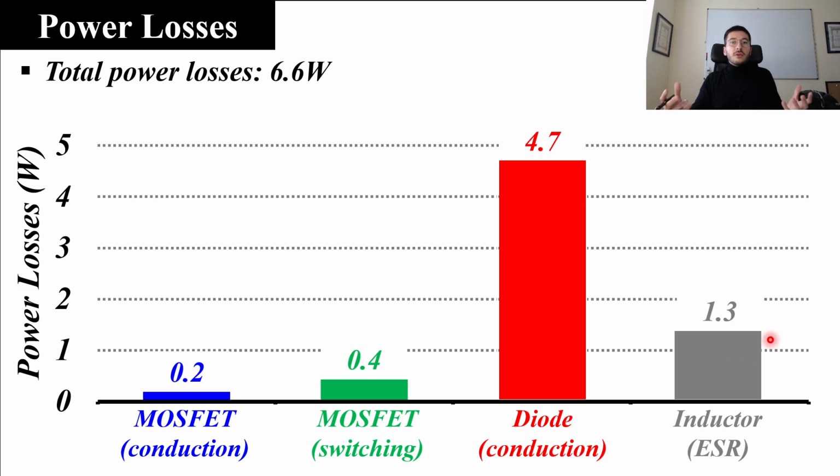Basically, because our model is very simple, we only have the ideal inductance in series with the equivalent resistance of the windings. So we only consume power in that resistance. It's very easy to evaluate the power consumption in that resistor in LTspice. So the final value is 1.3.